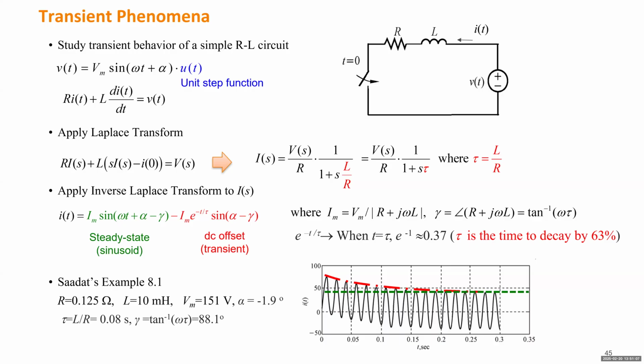Another way to simplify the analysis is we can categorize dynamics into steady state behavior, transient dynamic, or even faster sub-transient dynamic. In order to do that, we need to define some parameters, such as time constants, which tell us which dynamic we're really interested in. And next, we have so many parameters from the generator. We just need to select which parameter falls into which dynamic.